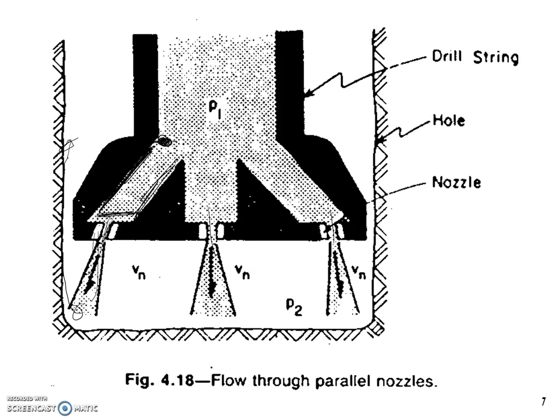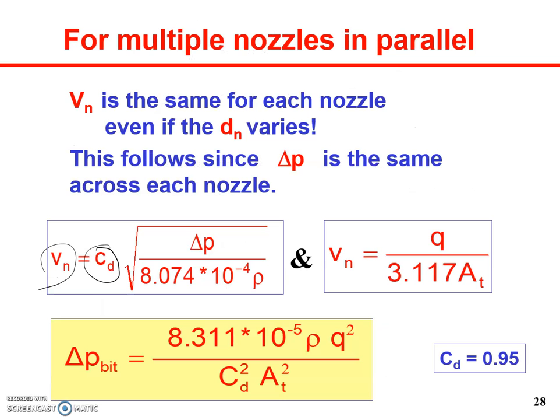So considering these factors, which usually are ignored in our modeling calculations, just specifically through the nozzle, we put in a parameter to consider those pressure drops, and this parameter is called CD. CD is a constant, and we use 0.95, suggested by researchers.